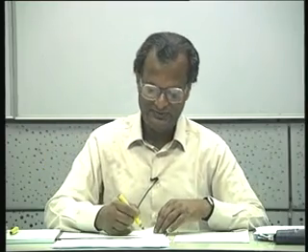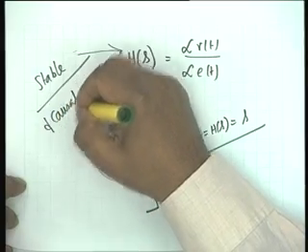And the other criterion, there are two criteria. The other criterion is that if you want a real time realization, that is, if you want to find a network which works in the laboratory, to a given excitation it gives a given response, obviously the network must be causal. It should not be anticipatory. Now what is the criterion for causality? How do you define causality, or how do you characterize a network to find out whether it's causal or non-causal?